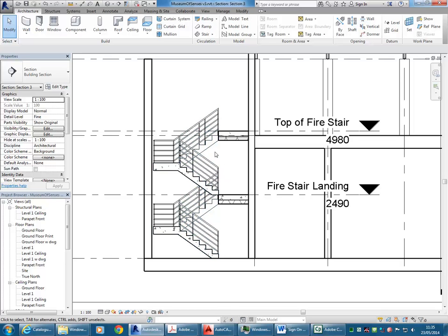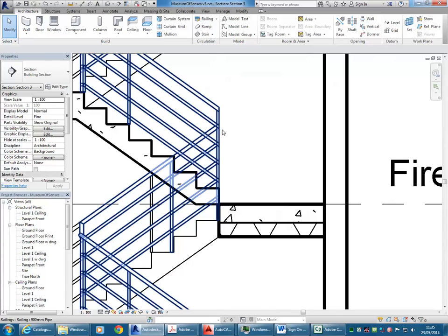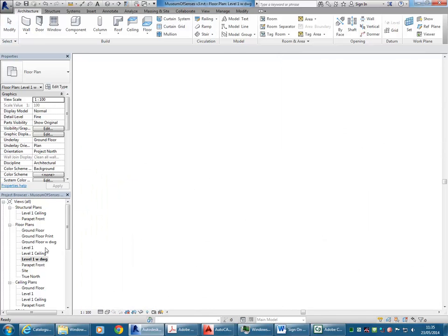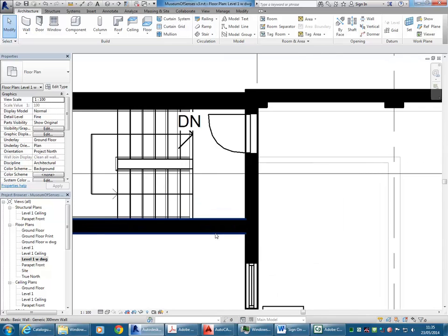You're looking at it from an elevation. In the actual, the stairs go here, the walls are there, there's free space here, but the railing would come across. You'd see the railing in section here. Probably they'd have that all the way across. You could finish it there though, and then have a railing there, and you would see that from the side in elevation. But structurally, that'd be difficult because you have nothing holding the floor up. Whereas if you take it all the way across, the floor can just be held up by the walls.